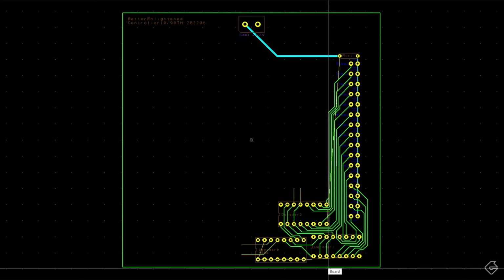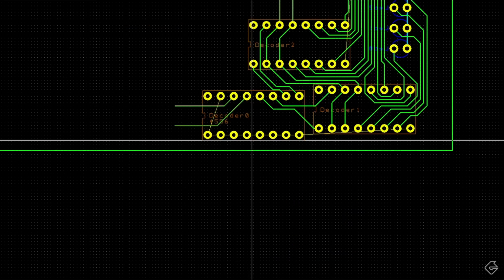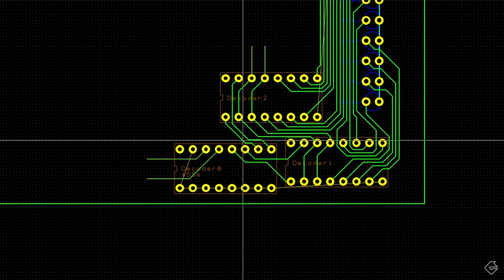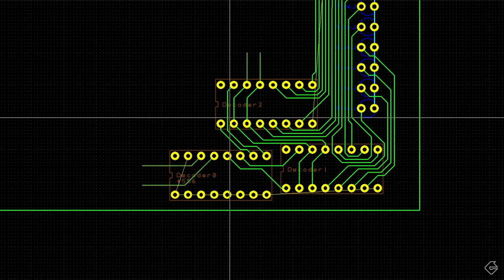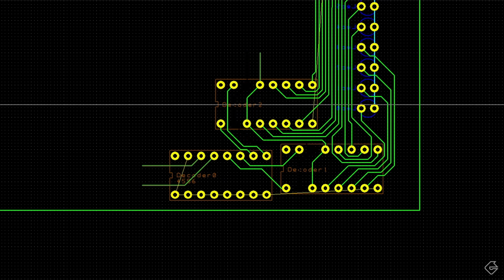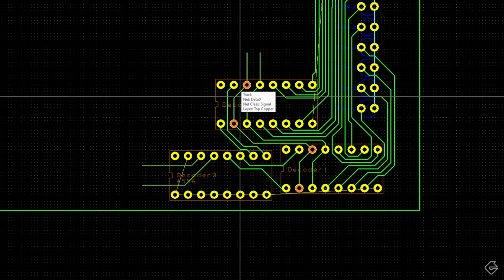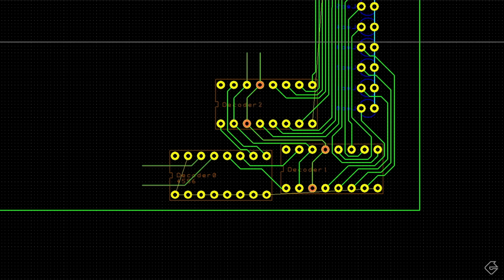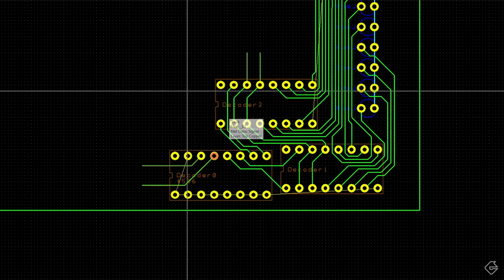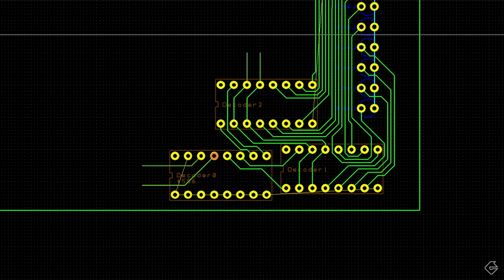So the next one, what I've done is I've basically thrown in a couple of other wires, and I've also added these little extensions. So what the heck is this? So there's data line 0, and it's connected across all of these decoders appropriately. There's data line 1, data line 2, and data line 3. I haven't connected them to anything yet because those components are going to come later, but I wanted to make sure that they stand out so we can all see where those external connections are going to have to be.